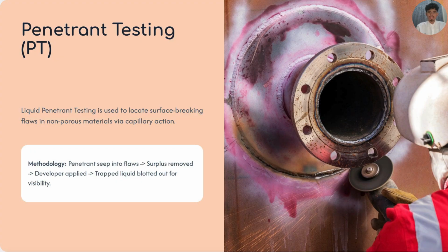So for the methodology, the penetrant seeps into the flaw, and then we remove the surplus, and then we apply the developer, and then extract the liquid, blotting it out for visibility. So let's check it out.